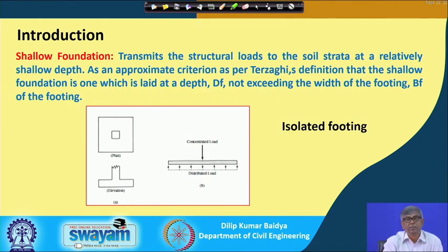And you can see the shallow foundation definition; it is not only a qualitative definition. A shallow foundation transmits the structural loads to the soil strata at a relatively shallow depth, and most shallow foundations will be within 1 to 2 meters, even less than 1 meter is possible.